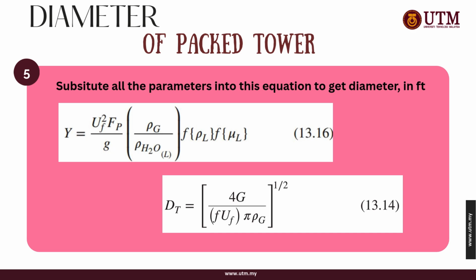flooding velocity UF. After calculating the flooding velocity, we're going to use the same equation as in step 1 to calculate the diameter of the packed tower. And this gives the internal diameter of the packed tower in feet.